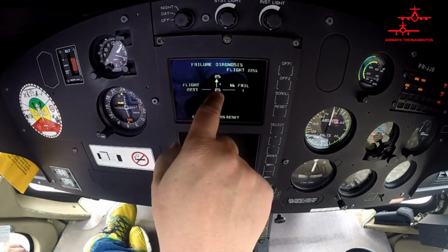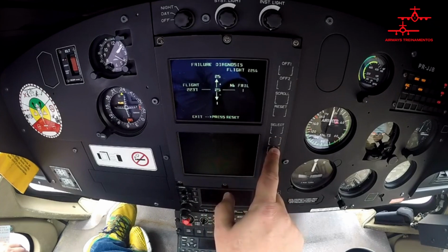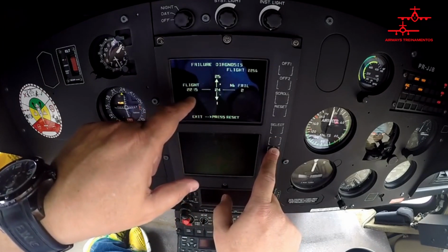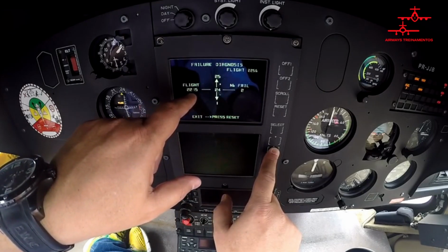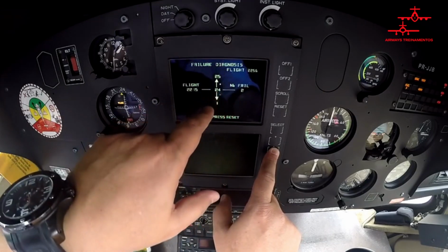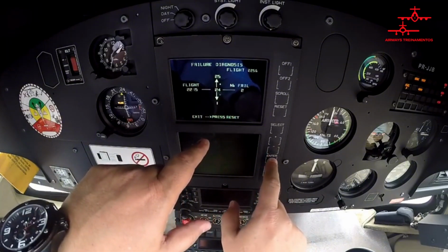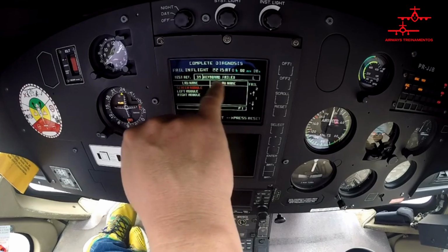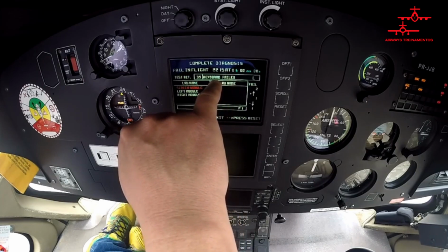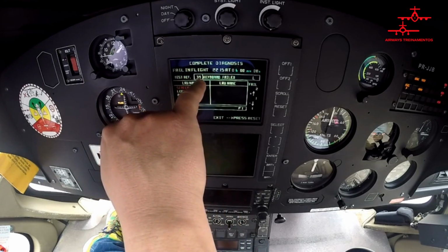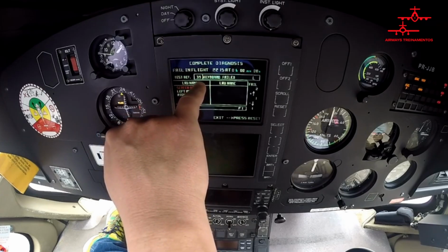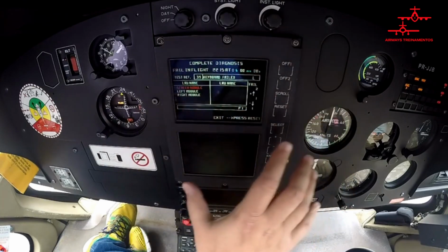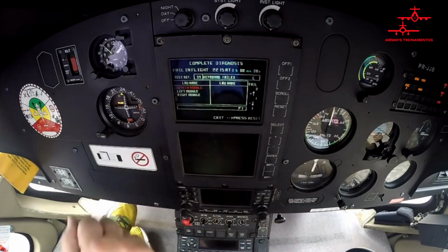That's the number inside. I can select here the number inside, these 24 faults. So fault number 24 happened on flight 2215, and there were 2 faults. To find out what fault this is, I press enter and then look at the screen in left-right mode, right? Or it said it detected one from the keyboard. Reference test 39, right? With this reference test, you go to the maintenance manual. Since the system didn't detect anything, it didn't show any faults. It must have been a momentary fault.